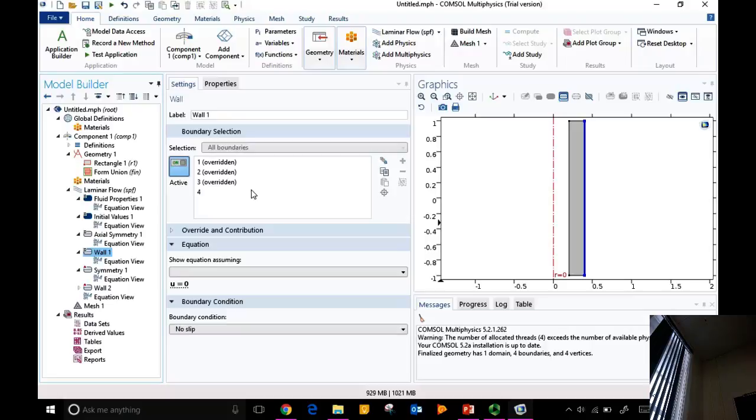If the fluid element near this becomes unstable and starts getting thrown around, then it will form these cells. So this is an unstable configuration. When the inner cylinder rotates faster than the outer cylinder, it's an unstable configuration. There is a critical rotational speed above which the flow will go spontaneously from 1D to 2D. So we have an R component and a theta component. You will develop an R component and a theta component even though you don't have one in the beginning.